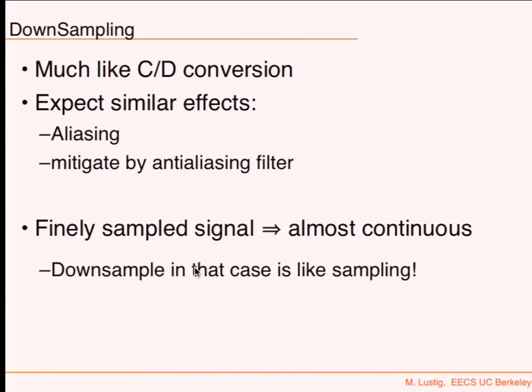It will be much more comfortable if you go down and present the samples at 48 kilohertz, or 44.1 kilohertz, or 24 kilohertz, or something slower. Otherwise, it's going to really be upset. It's too much. I don't want to deal with this. My hardware is not ready for that. It's not going to work. So you'll have to downsample.